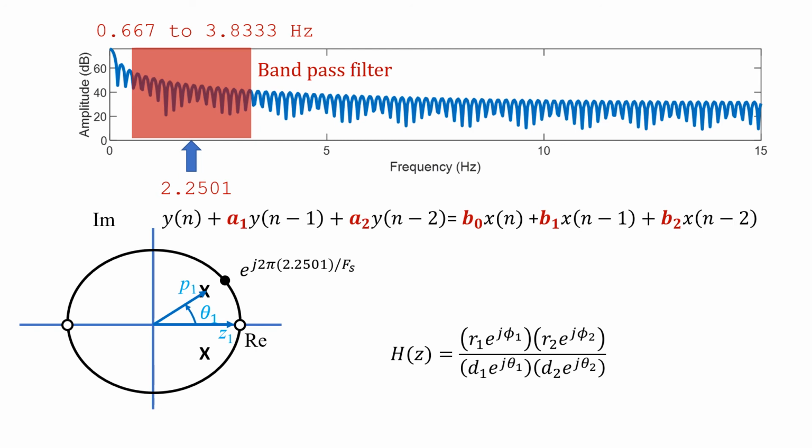Now my difference equation that identifies the filter that I want looks like that, second order, and as I move towards higher frequencies, as you can see, there will be a point here when I'm approaching the highest frequency of 15 Hertz, where that little distance here corresponds to this distance in the expression, and it will lead to 0 at the very highest frequency, which is some frequencies that I'm not interested in. I was just interested in passing this part.